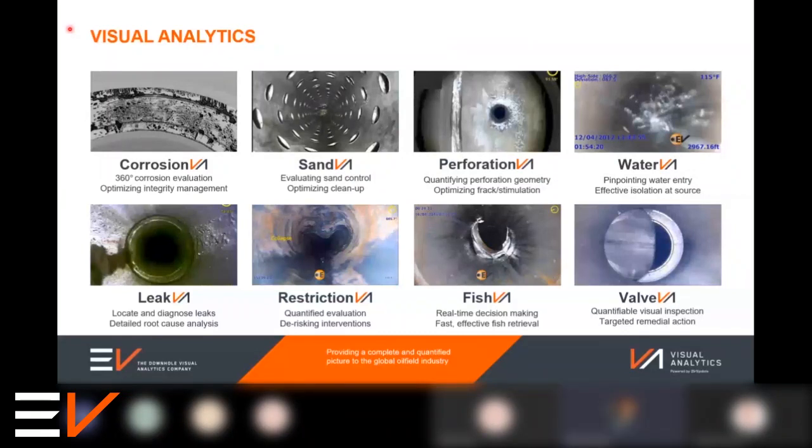Hi, Tobben. A few questions actually came in through the chat, but Glyn was proactive in replying to them. One question came in from John Lassick, asking whether we calculate the beveled entry area, and Glyn replied mentioning that we measure the exit hole on the pipe OD, and the beveled area is considered in the visual assessment we make for each perf, but isn't quantified. Was there anything else to add there, Glyn, or did that really cover it?